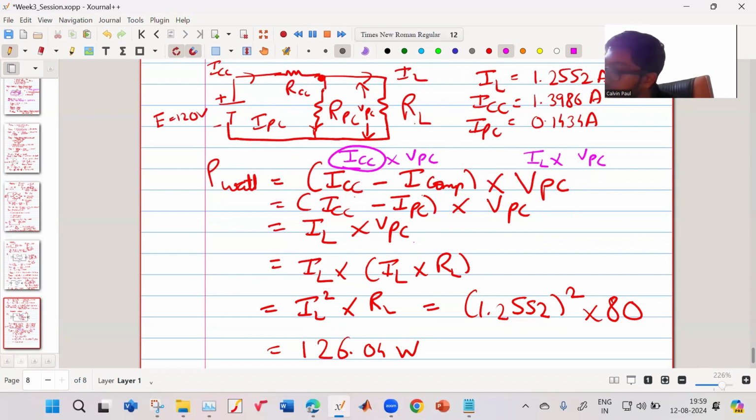So what we did was we connected a compensating coil mechanically into the wattmeter such that your ICC current will be compensated with the extra current which is flowing through your pressure coil, such that the effective field which is generated by your coil will be equal to your current which is flowing in your load resistor. Okay, so this is the function.